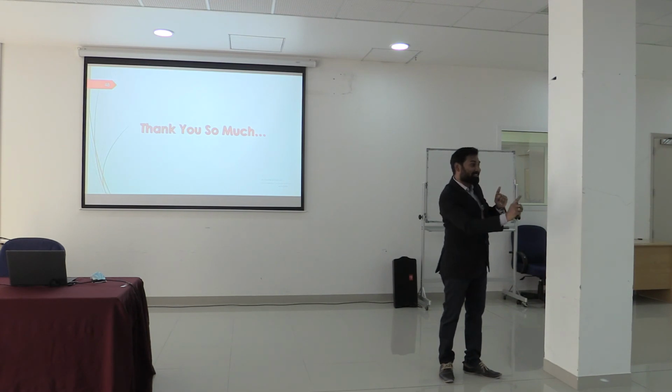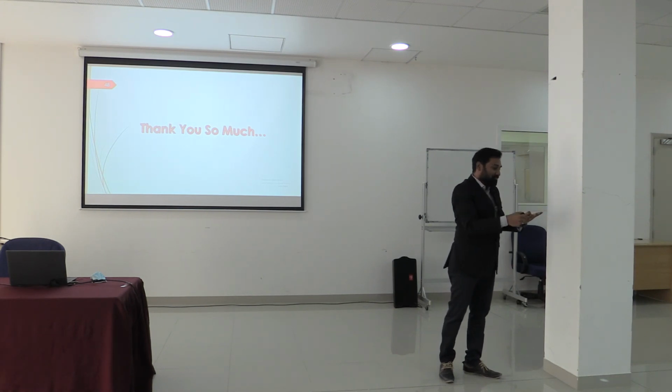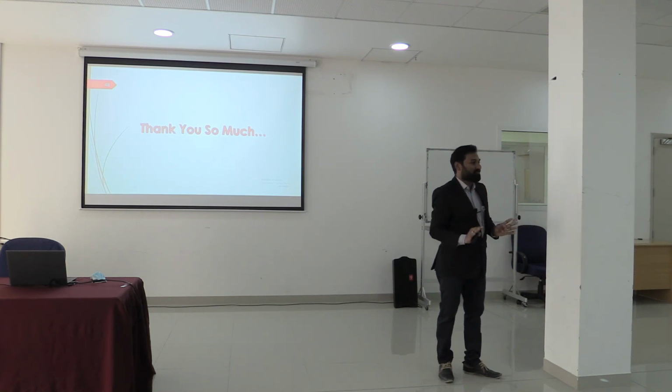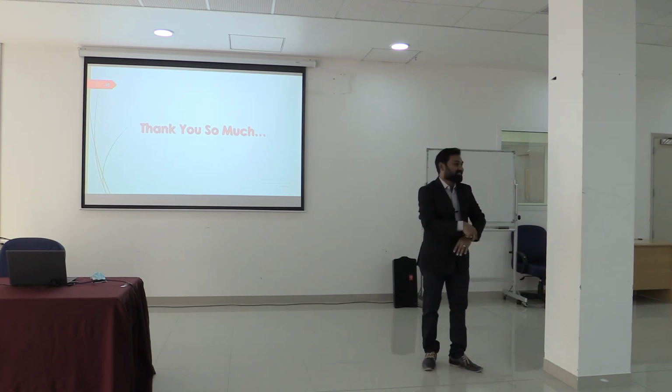You are creating multipath. The scattering also multipath scattering. This is a MIMO channel, sir. Same information is transmitted in 4 pathways. So if one goes deep fade, the other will not fade. That is the concept of diversity. That is the advantage of 5G. So one channel goes deep fade, at least the strongest signal will reach or will go with any of these 3. If all 4 channels are distorted, you won't get information. Even there is no guarantee for that. That is the concept. Yes, sir.